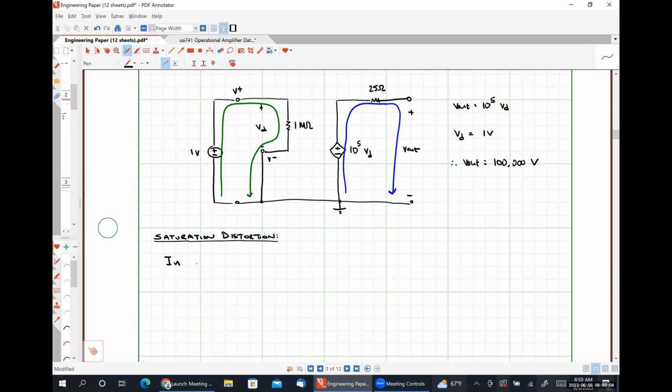So in a real op amp, the output voltage cannot, I'm going to put a little asterisk there because we'll talk about it in a moment, exceed the power supply voltages, okay? So when the output signal is constrained to be between VCC plus and VCC minus, we call this a rail to rail op amp.